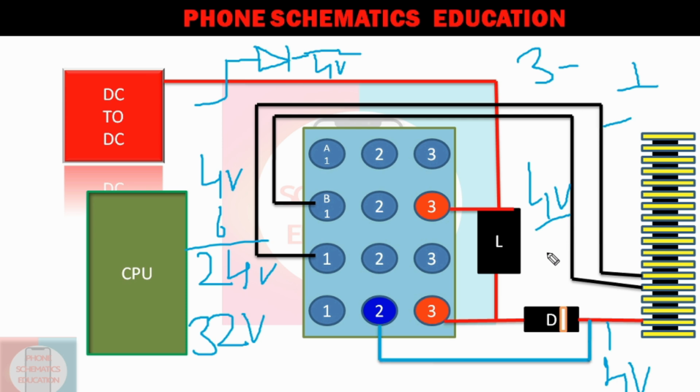So how does this light work? For this, we need maximum voltage. That's why in this line, when everything is okay, you will get 15 volt to 42 or 45 volt according to the circuit of your phone, right? Now this happens after the switching.